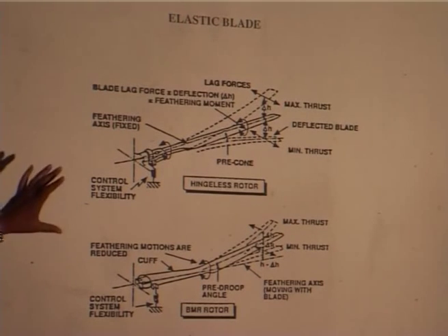And so, this is just a picture showing how one load will affect something else, pitch angle, based on the deformation in another mode. So, you see flap deformation, lag load affecting pitch angle. Similarly, lag deformation, flap load influencing pitch angle. Now, you see, if you want to analyze the problem, you can't neglect anything. You have to have the flap, lag, torsion problem, which is very complicated. So, we are not going to do that in the course, but this is just an